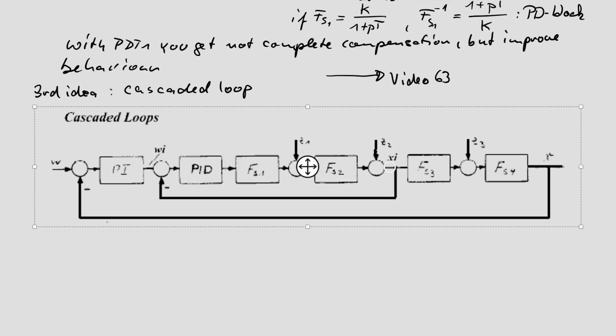That could be not so easy to add, but this is a condition for a closed loop system with cascaded loop, that you have an internal sensor for internal variables. If the sensor gives a value, then you can add it as internal negative feedback.